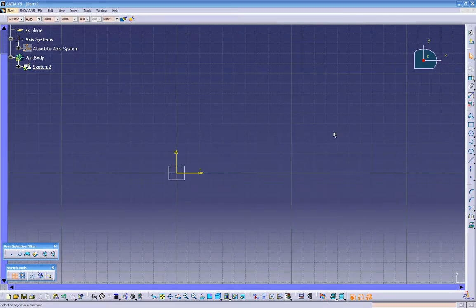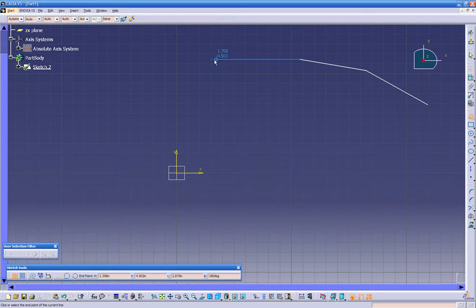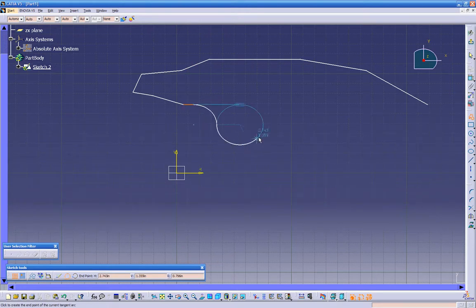So we can create just a quick rectangular. You click on the rectangular, and you see we have quite different options over here we can create. It's a profile. This will create multi-lines. If you just snap it, you can create a line. But if you snap and hold it, it creates an arc. So snap and hold, then a quick tap goes line, line, line. Then if you hold it and drag it, it creates an arc, the direction you like to go.